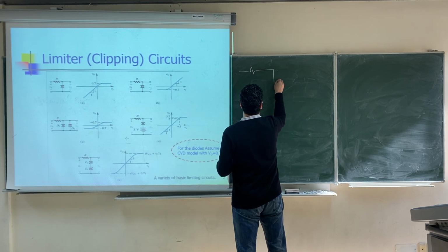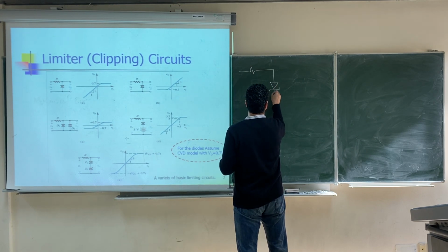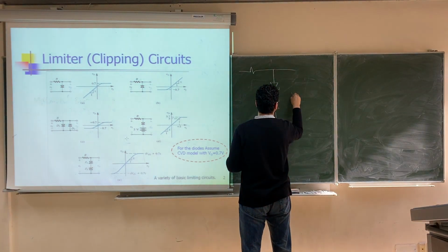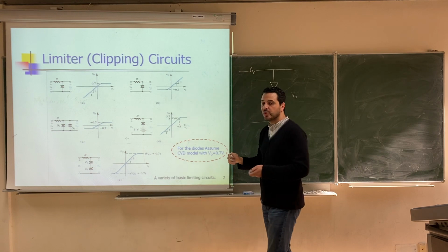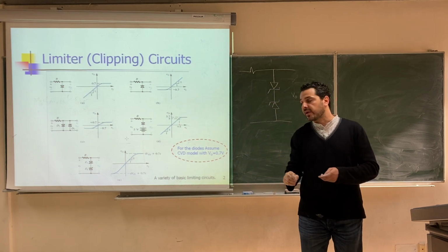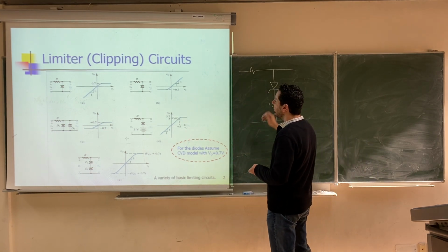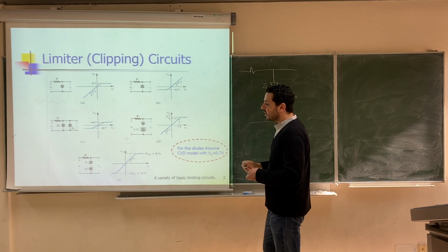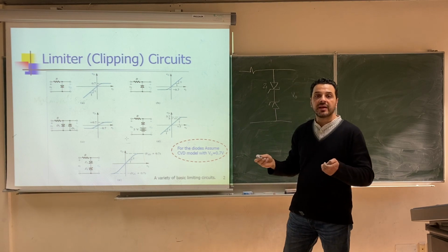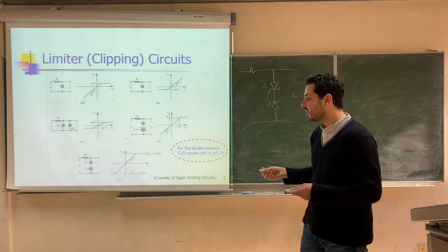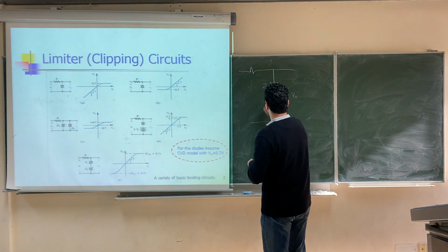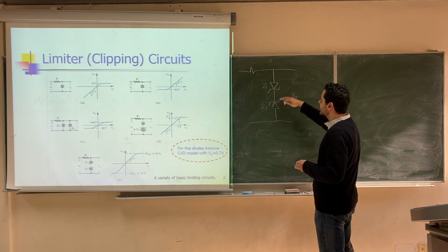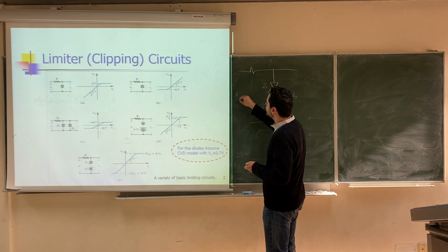We have the circuit. It looks like this. This is V out. And let's assume constant voltage drop model for both diodes, okay? With 0.7 battery, and let's assume that Zener number 1 has a breakdown voltage of VZ1, and Zener number 2 has a breakdown voltage of VZ2, okay? So, we ask ourselves, when would this branch be off?